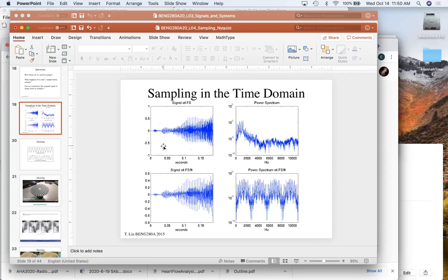When we look at the same signal, but we drop the sampling rate by a factor of 8, then the picture, when we plot those sample points, actually looks different. When we take the Fourier transform of this, we get the power spectrum, but we get replicants of the power spectrum that are separated at that replication rate.